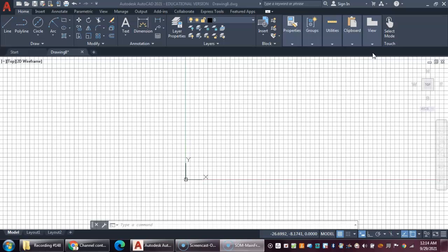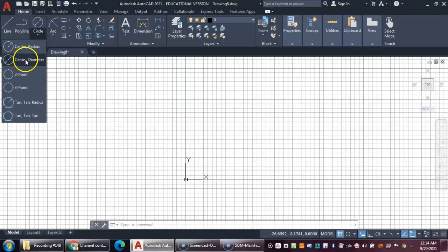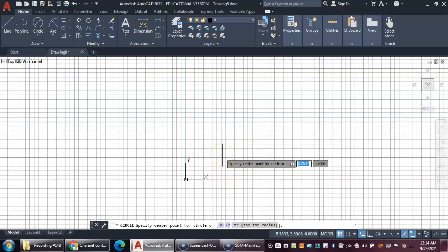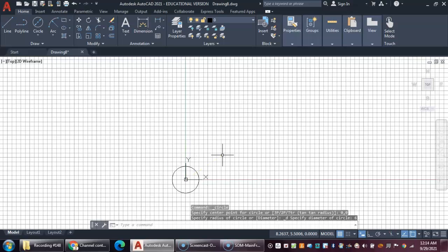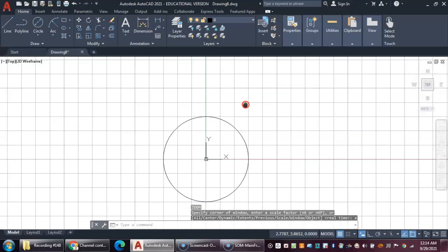to use the center of any type of wheel or spoke or axle as 0,0. So I'm going to go ahead and we are given a diameter of 6 inches on the outside diameter and an inside diameter of 1.5. So we'll go ahead and use the circle diameter tool here. Again, 0,0 will be my center, and 6-inch diameter for that. So let me do a zoom all to come in on it.